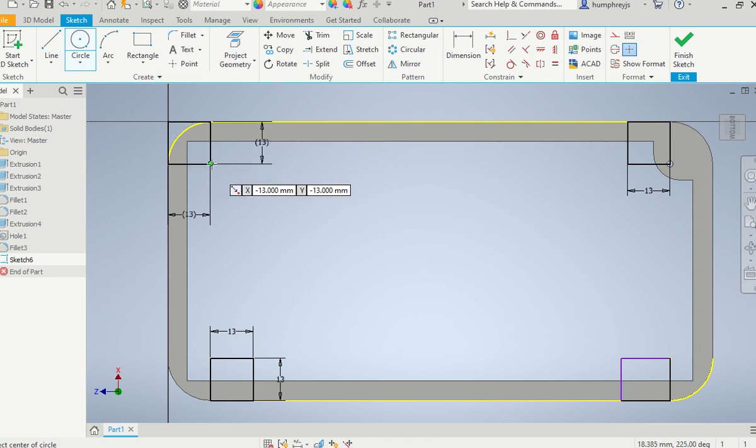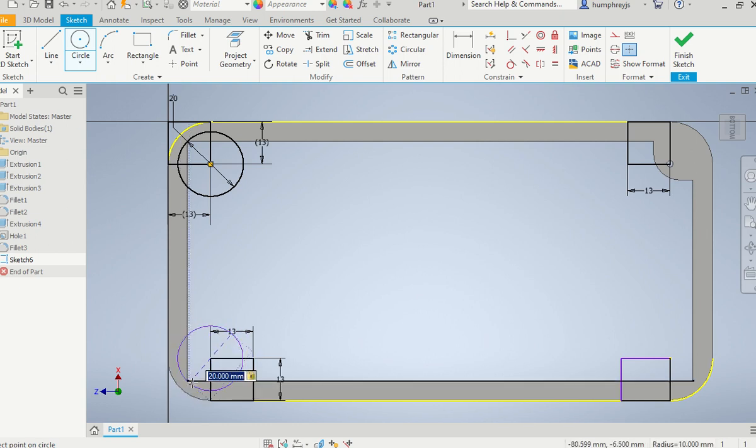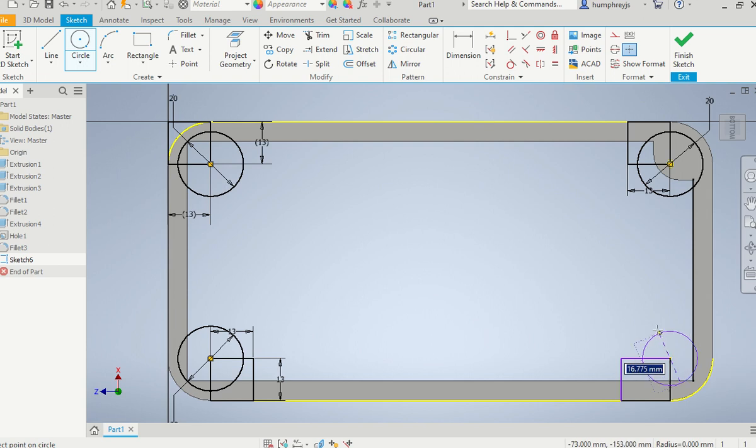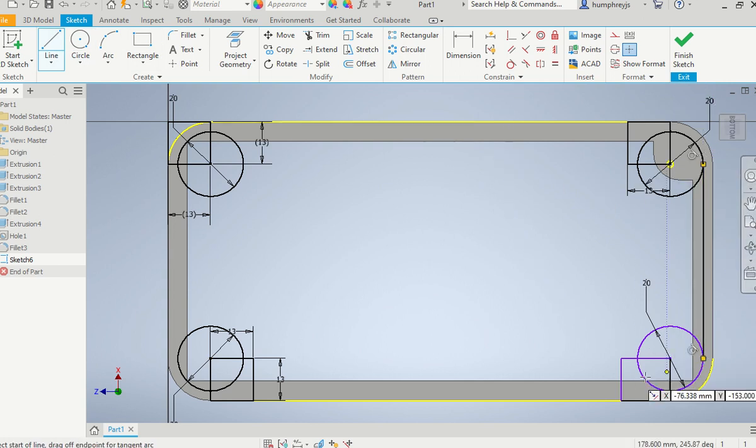So back in we go. Last time I used a fillet tool for this. It's a diameter, so I'm putting it in as 20, radius 10, diameter 20. Okay, and from here, 20, tab, 20, tab. And the reason I'm just showing you this, it's quite a rudimentary way of doing it, but just so you know, you can make shapes as well. It's going to lock onto that right hand side, it's going to lock onto there. Exactly the same thing is going to be happening here.